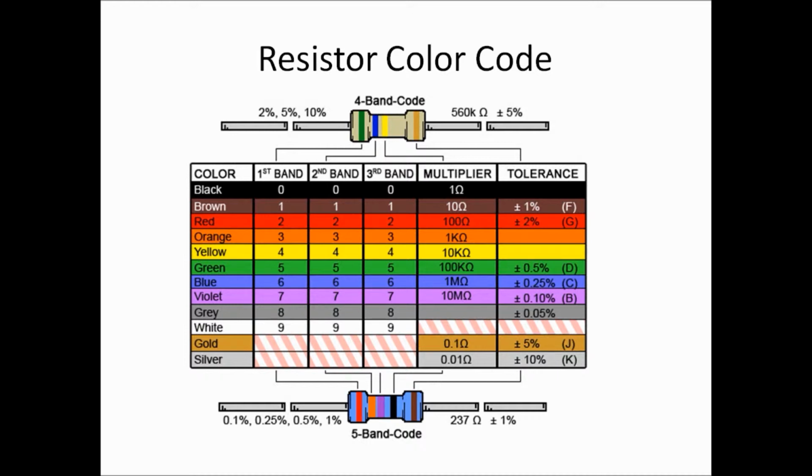So on a resistor, there's color bands. If you have one around, take a look at it. You hold it up and you look at the first band. The first band is not the one that's gold or silver; it's any other color than that. The silver, gray, or gold band is the last band.